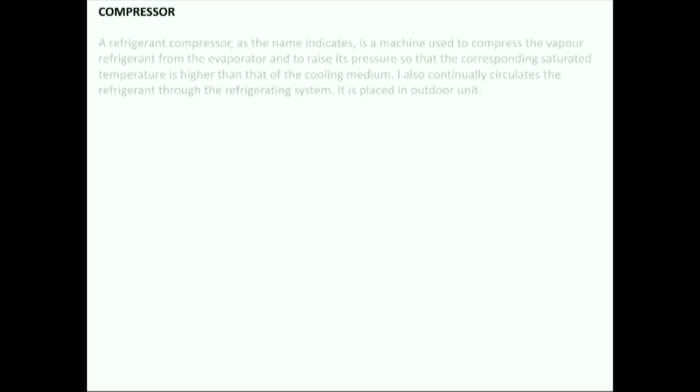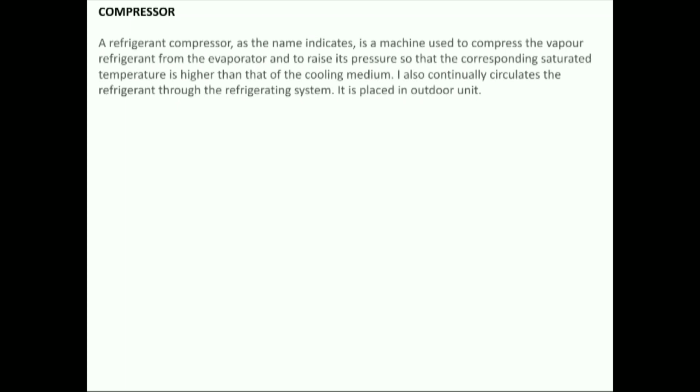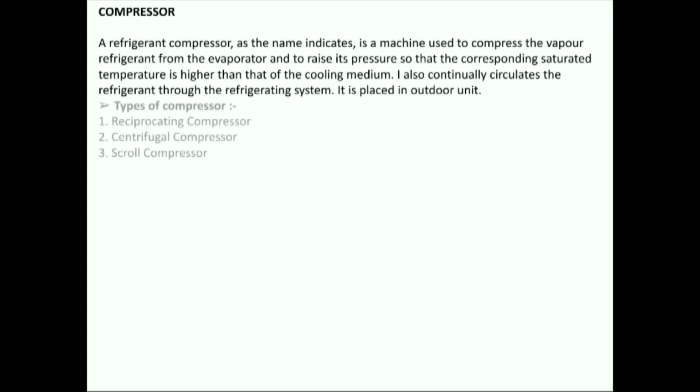Compressor. A refrigerant compressor, as the name indicates, is a machine used to compress the vapor refrigerant from the evaporator and to raise its pressure so that the corresponding saturated temperature is higher than that of the cooling medium. It also continually circulates the refrigerant through the refrigerating system. It is placed in outdoor unit.